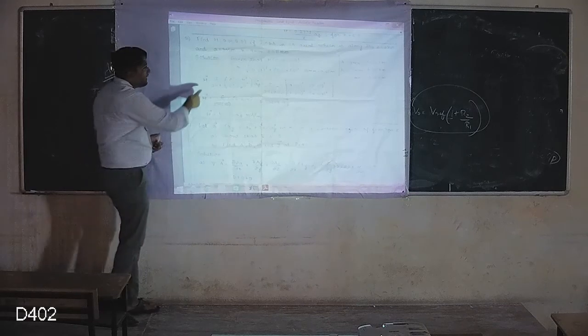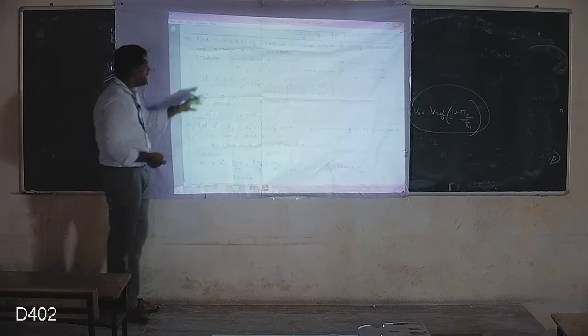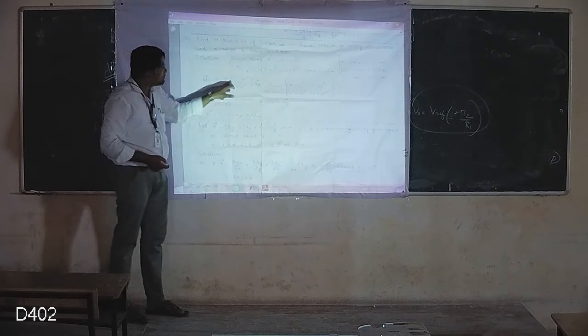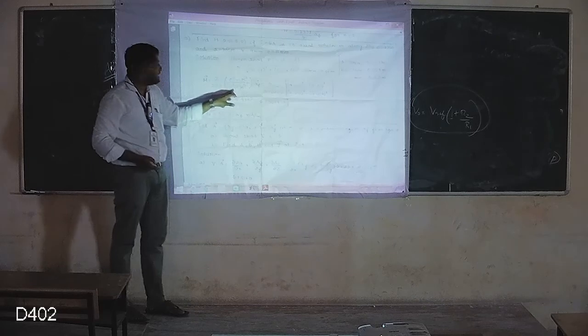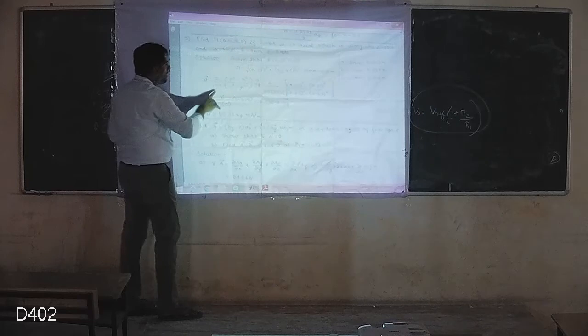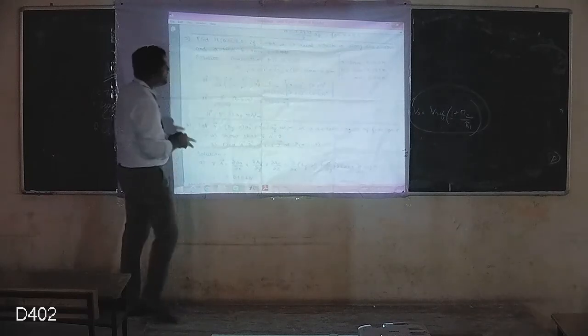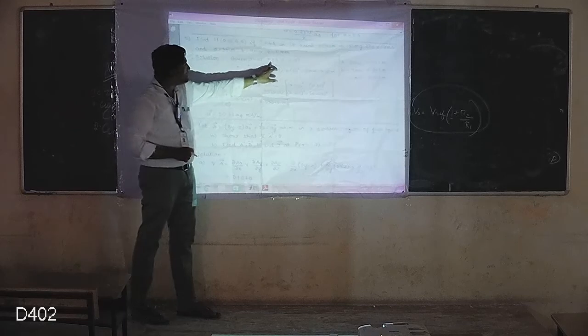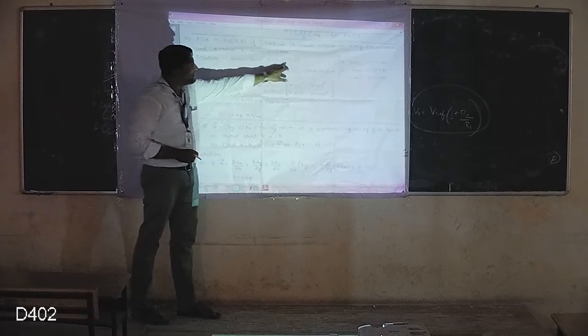So here we are calculating only for region number 3, and the formula is I divided by 2 pi r times c square minus r square divided by c square minus b square. With a, b, c given, I have to find r at this point, because I am going to obtain the magnetic field at the point 0.01 comma 0 comma 0.